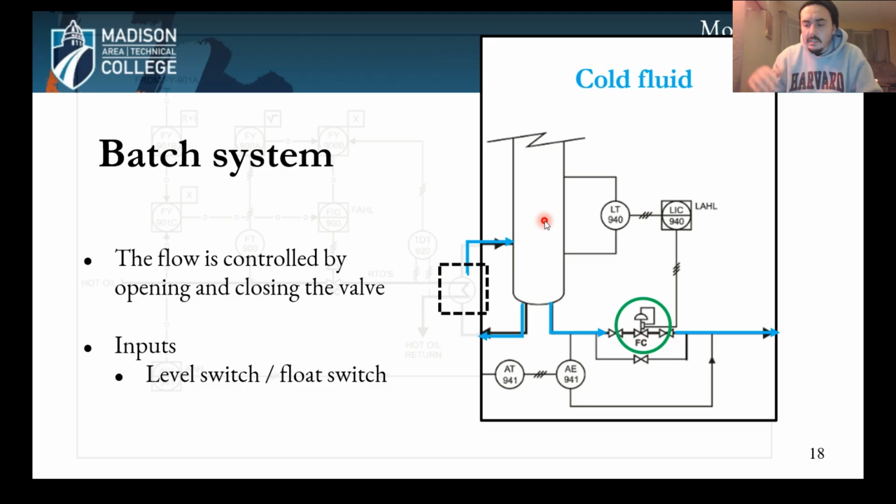So it's got two states. It's got a state where it's basically hanging. There's a joint or something like that typically, and there's no liquid. So as the liquid rises, like I said, the material is less dense. The liquid rises and it pushes the switch up, and then now it's in its second state. So this is typically its on state. So off as the fluid's here, on as the fluid's here.